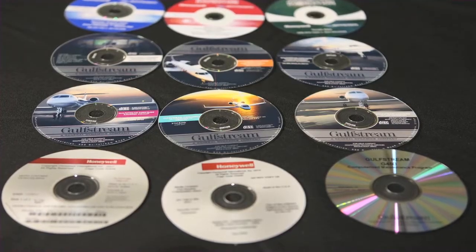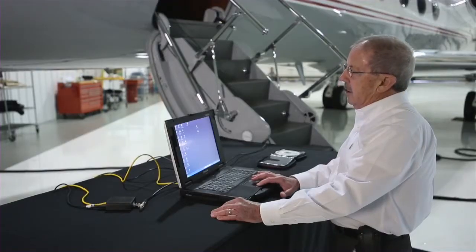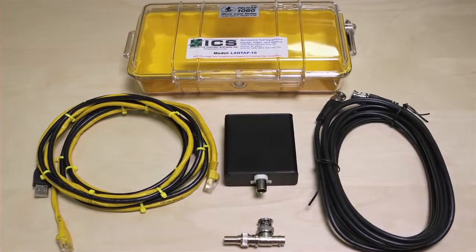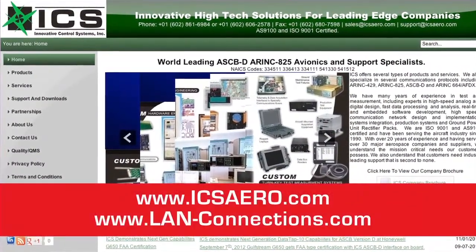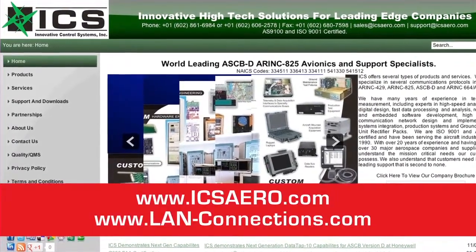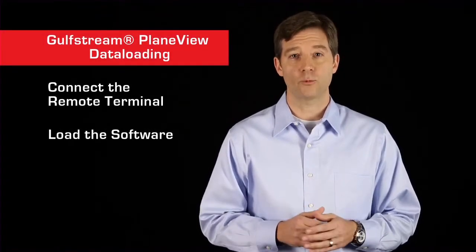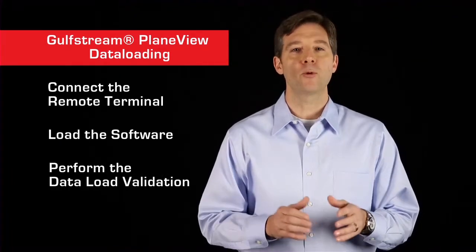To perform this task, you'll need the updated software, the remote terminal, and an interface kit like the LANTAP 10. If you don't have one, you can order it online from ICS Aero or Land Connections. There are 3 steps you should follow when updating the databases. Connect the remote terminal to the aircraft, load the software, and finally, perform the data load validation.